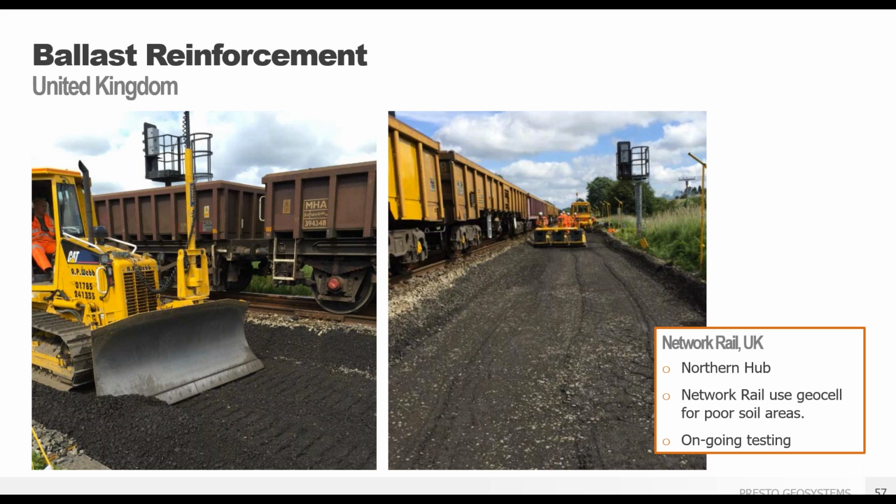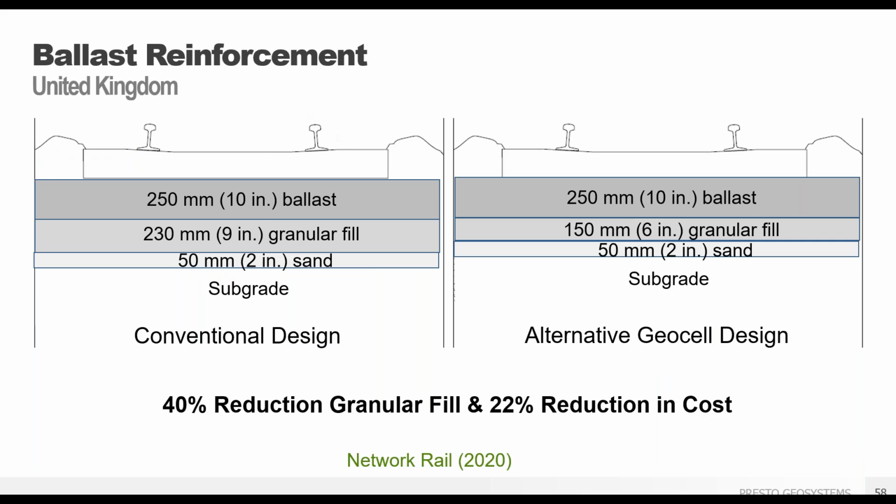So their in-house team did some numeric modeling along with our PRESTO design method, and actually with the University of Kansas testing that I showed you before. That modeling was used to quantify the reduction of the track bed if GeoWeb was used as a solution.